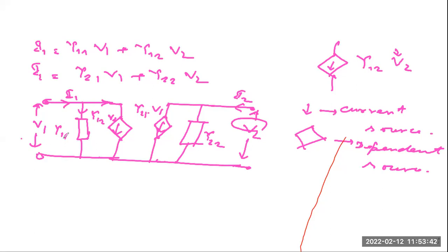So now you see, this admittance into voltage is correct. So that's why this is this parameter. It means this particular portion, Y12 into V2, is this current. So that means the source current I1 equals Y11 into V1 plus Y12 into V2.